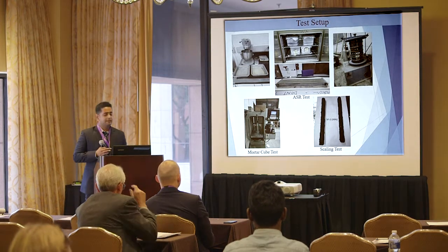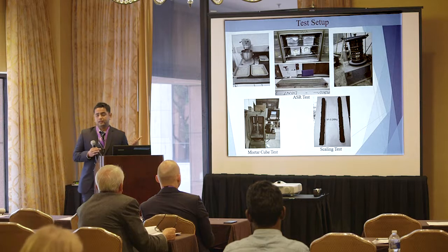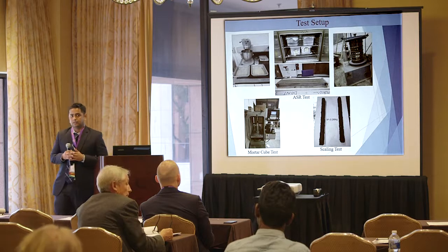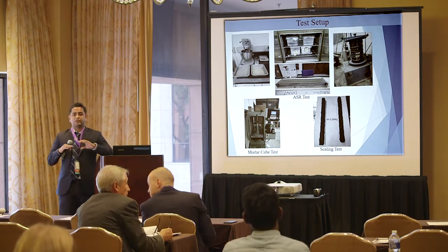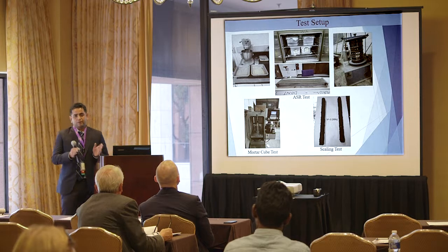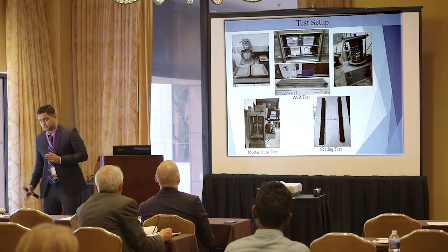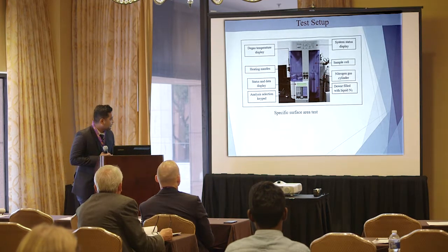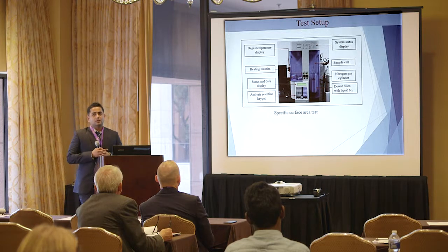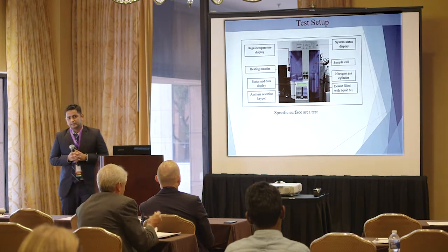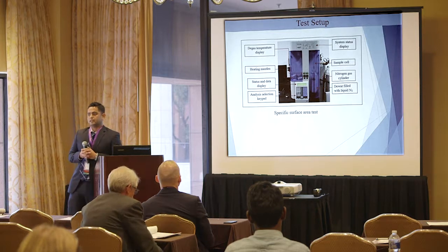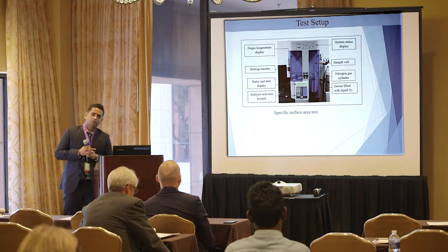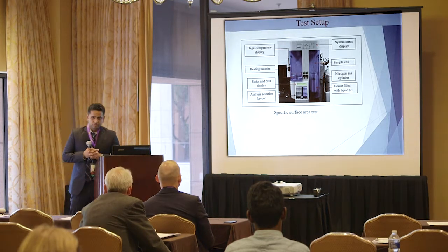And for the scaling test, according to ASTM, there is a specification that the scaling test should be done on the real surface of a concrete slab. Apart from that, I conducted it on mortar bars. And this is the specific surface area test. I followed the analyzer to see how the particle size varies, and I followed the BET procedures for this test.